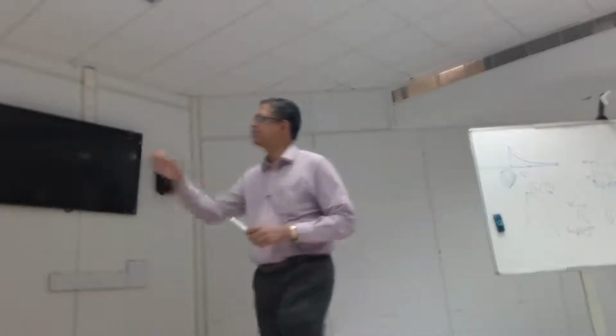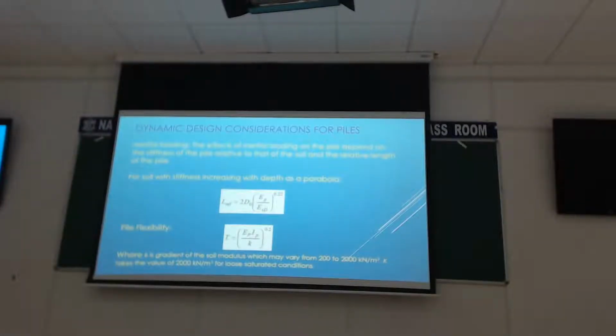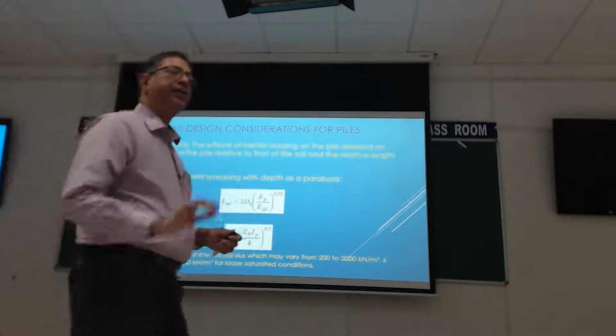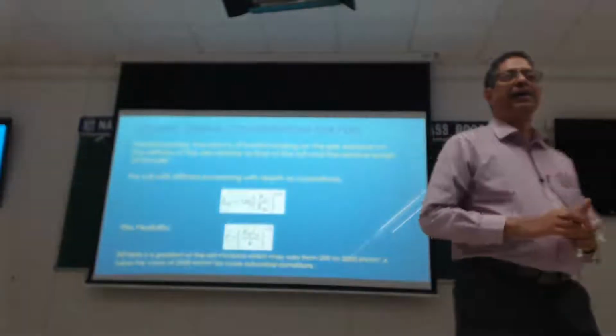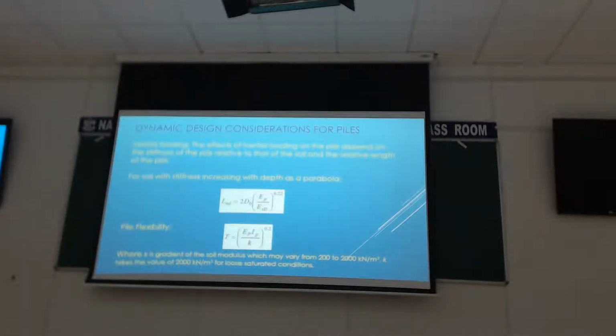But what this increasing stiffness does is, we are trying to work out this factor L, which is like working out an equivalent length, which depends on the diameter and the ratio of the Young's modulus of the pile to the Young's modulus of soil.